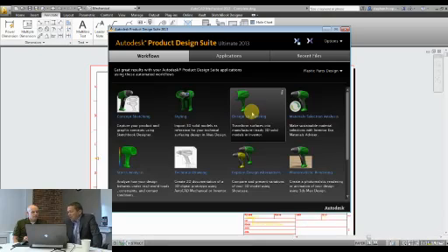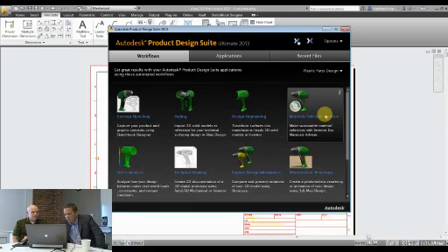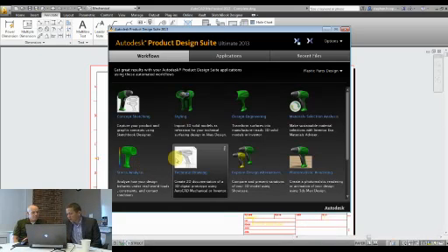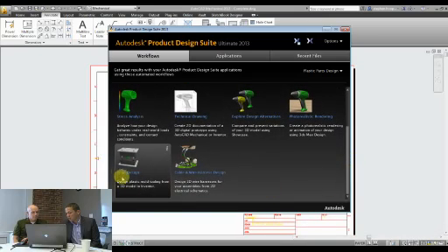Next, you would probably need to engineer the product. So you'd need to have the PCB boards integrated. You'd need to make the mechanical mechanism for the wheel on the mouse. You'd probably want to select materials that were ecologically friendly for the environment. And then you'd probably want to stress out the model to make sure you can take all of the structural loading, similar to the optimization that we did earlier. Exactly. You'd want to create technical drawings, visualize the product so that you could sell it in the marketplace, as well as being able to create the mold and tool die for production that we discussed and integrate the electrical elements of the design. So all in all, it's the whole process.